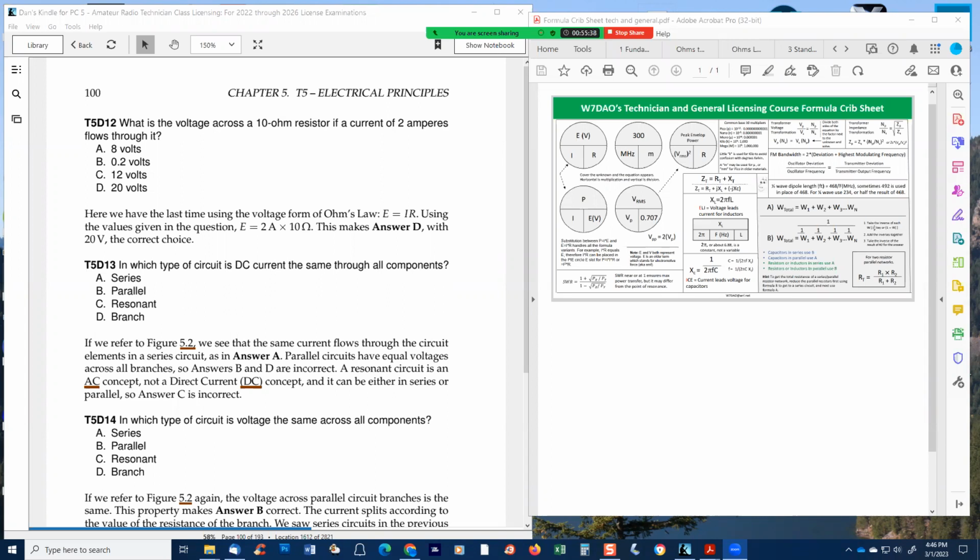It's not like a battery where it's just steady. And one thing you want to do is to smooth that out. There's devices you can build. It's simple wiring with diodes, which act like check valves. You build a device so they all appear the same way, but you'd have a bunch of power, then nothing, then a bunch. And by using capacitors and inductors, you can have those voids fill out till finally the current looks level and steady, like you get from a battery.